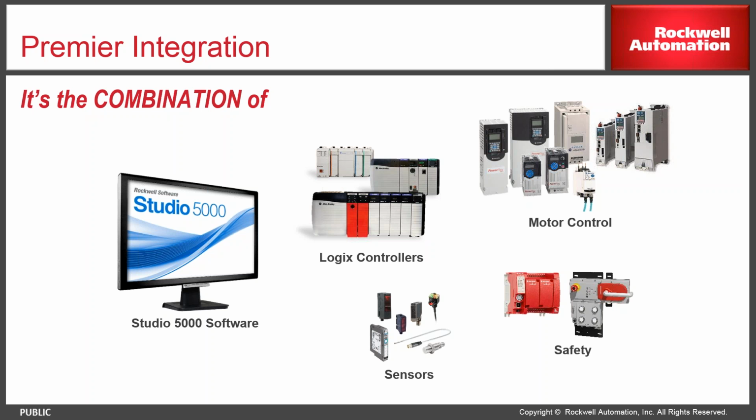So when we are talking about design, we have an experience that we like to call the premier integration. It's actually the experience of integrating the Allen Bradley smart devices into the Allen Bradley Logix control platform devices. Okay. So it helps the operation and maintenance people to actually get a number of advantages. So when you look at it from a design perspective, you get the advantage of automatically mapping of the data objects. So this can eliminate some of the address mismatches.